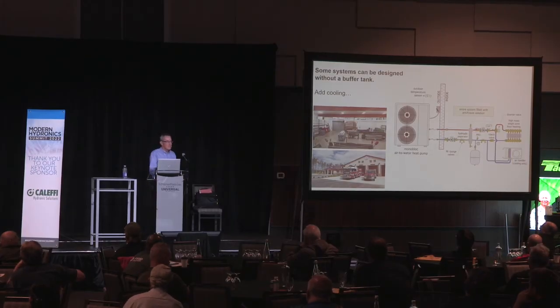And by the way, if you want to go to a client, think about some of these metal fabrication shops. In the summer it's 100 degrees in there, they're sweating, they don't have cooling, or maybe they've got a window shaker or something like that. You've got a heat pump. You can give them chill water cooling with an air handler.